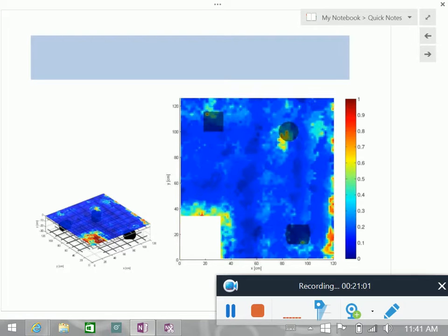So which one do we need to pick to do the analysis? This is not the case here, because this is one single slab. You don't get two very large peaks. It has to come from somewhere. I hope that you learn in this class that this kind of resonance is coming from some geometry. So if you only have a slab and you get two peaks, that means that something else is going on. In this case, the frequency wasn't giving any kind of information. You would only get one peak because it's a single slab.